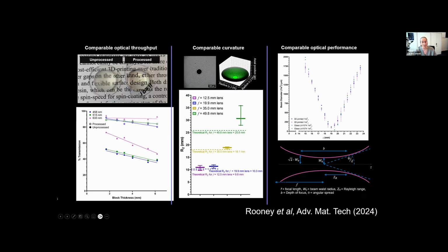And when we use our clear, transparent resins, we end up with a preform that looks like this unprocessed lens in the top left-hand side. Following a simple spin coating step, this makes this rather diffuse-looking lens optically transparent, and we can get lens transparencies in upwards of 90% without any additional coatings. And they compare very favourably to the commercial off-the-shelf components.